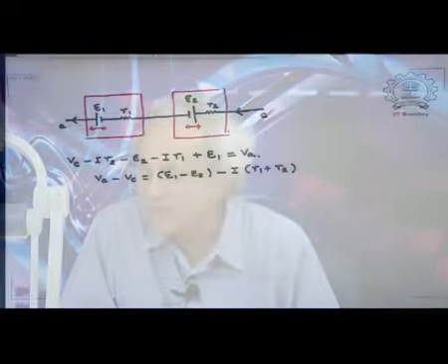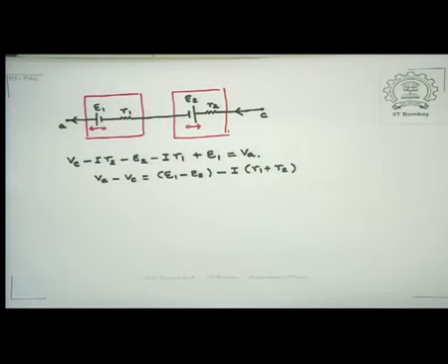Now the question is, this combination that we have shown here is not really a preferred combination. You will find that in all appliances where you use serial combination of batteries, the terminals that would be connected would be the negative terminal of one with the positive terminal of the other. The next question that we have is, why use a serial combination of cells at all? Why not simply use a cell which supplies a higher voltage?